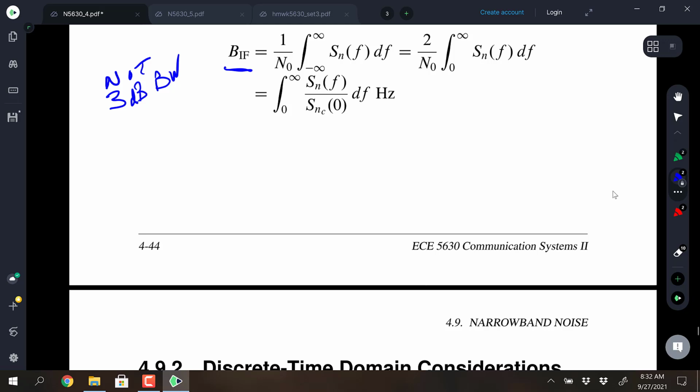If it's noise equivalent bandwidth, then you're good to go with all your analysis. If it's not, then that engineer has to tell you what the frequency response is of that IF, and then it'll be up to you to numerically integrate it, like in the top line up there, to get the noise equivalent bandwidth. Does that sound reasonable?